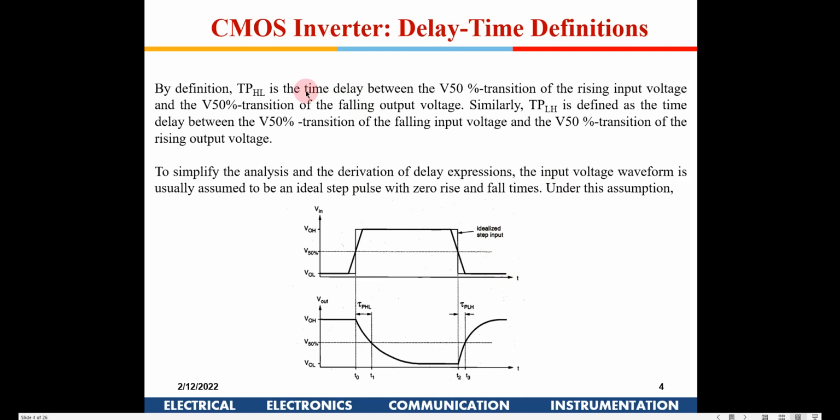Yeah. So when we talk about the load capacitance for an inverter, it should be based on the fan out, or the input capacitance of the device that is being driven by this device, right? Yeah, correct.